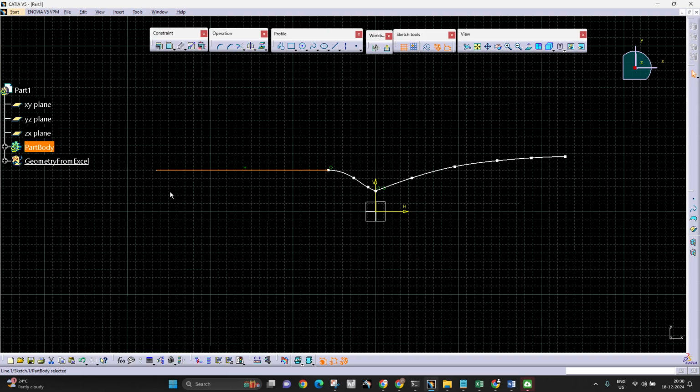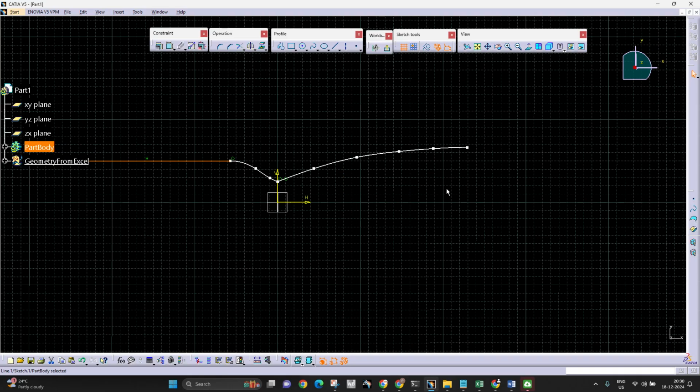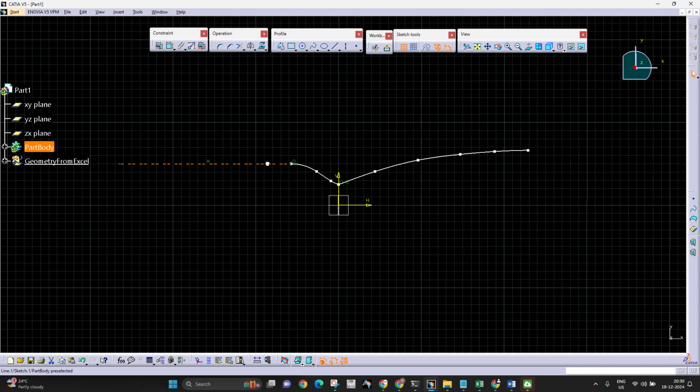You can do it regardless of any sort of equations. You don't need any equation for designing the convergent area or the combustion chamber length or anything. All you need to do is make sure that over here it is exact Mach 1 and the divergent curve should follow MOC principle in terms of curvature. That's it. Now let this design be as it is.